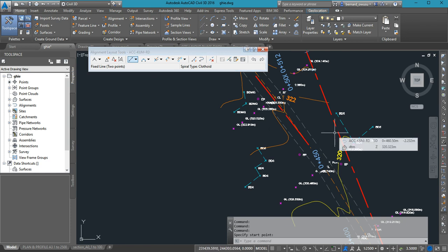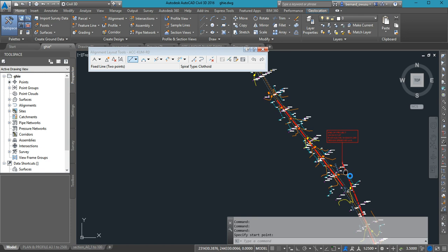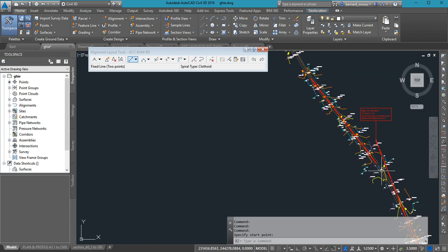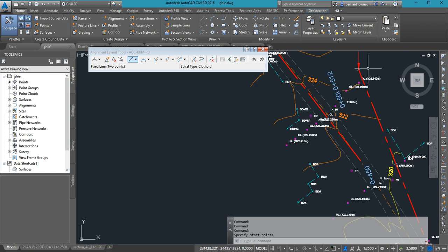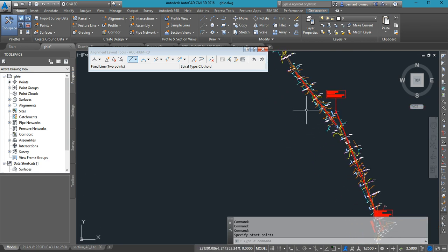It's like you are drawing a line through the center. So specify the start and the end of the second tangent, just as you did for the first. I shouldn't start from where the first one ends? No. If that is the correct position, no problem. But if that is not where it ought to start, don't worry. Look at mine. This is not starting from where this is ending. And my interest is the existing road. I want to define a center line which, as much as possible, will follow the existing. Please, are we okay? I want us all to have the 2 tangents. Then we will continue.